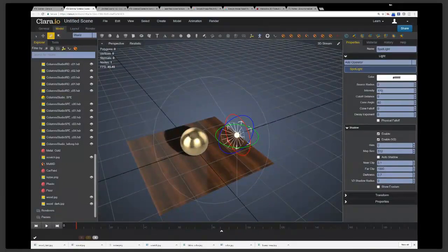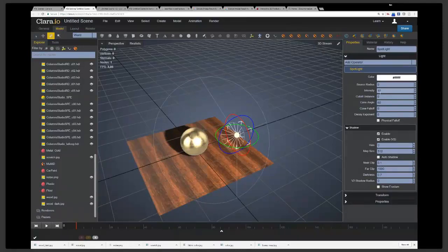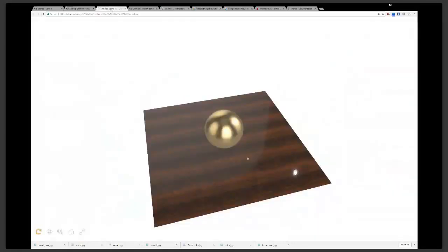There's actually a more accurate shadow calculation in V2, and that's what I got caught up with. We're making everything more accurate in V2, and we're trying to get almost all of that working in V1 so that the transition period is very smooth. But that's one of the things that isn't as fully accurate. In V1, shadows are just dark, even if there's light coming onto that point, whereas we calculate shadows correctly in V2, in that the IBL is actually everywhere here, and it wasn't a physical light.